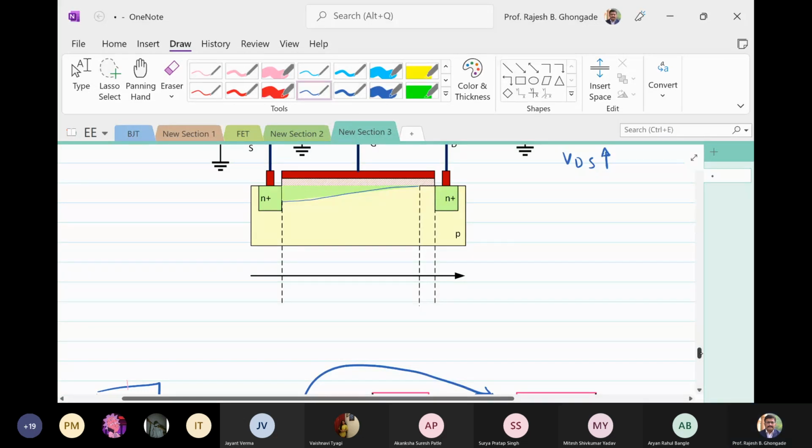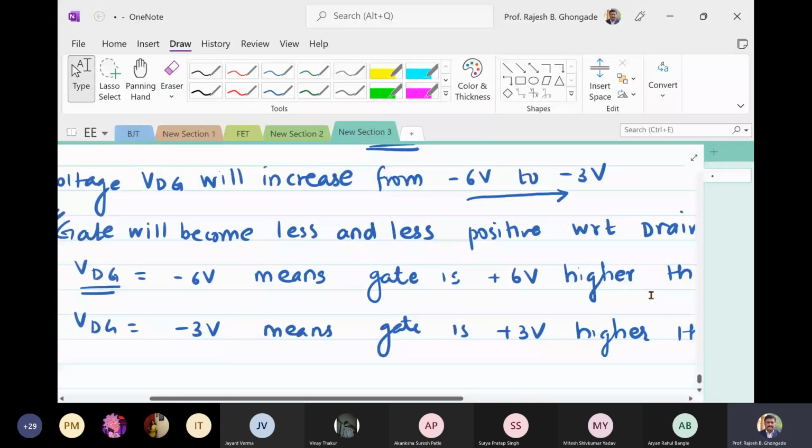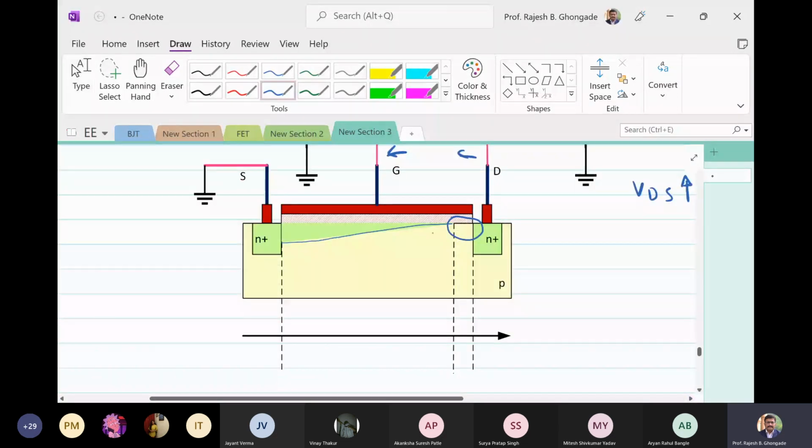Now you will ask, how is the drain current flowing? That should be the question asked by you. So the answer to that is, basically we have a very large voltage difference or electric field. Let us say this width is very small, or the voltage difference at this point and this point, that is the boundary, is comparatively large. So the electric field will be very high.